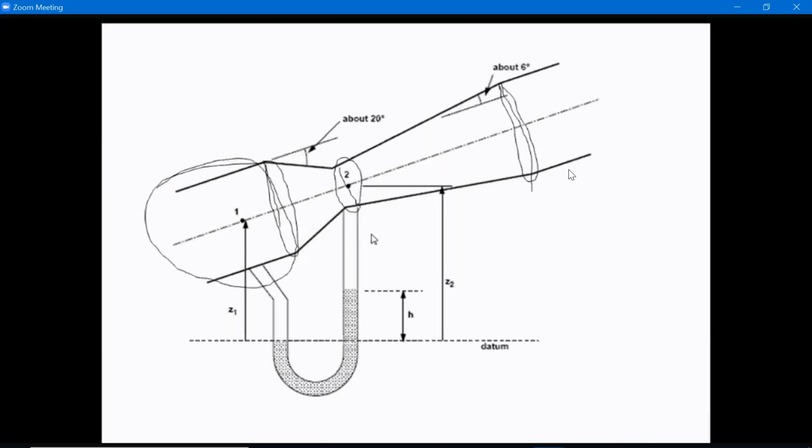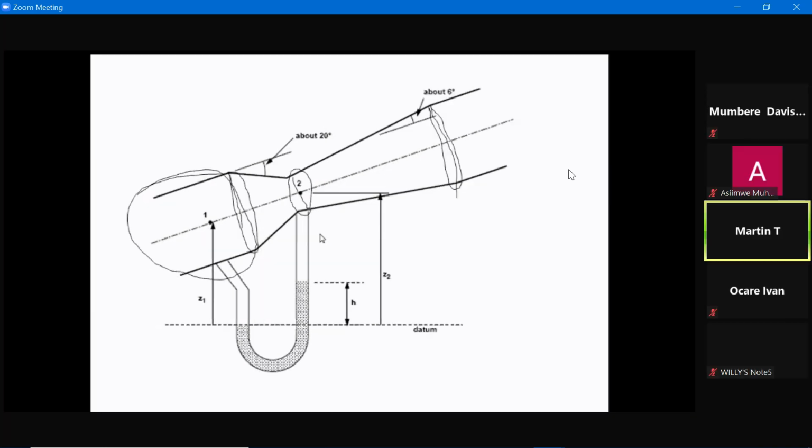And we have a diffuser. We gently take it back to the original cross-section area, so that you avoid more friction loss and also pressure losses. There are some pressure losses, as you study in pipe flow: when you change cross sections and the changeover is not smooth, then you create eddies, some eddy currents, which lead to pressure losses.